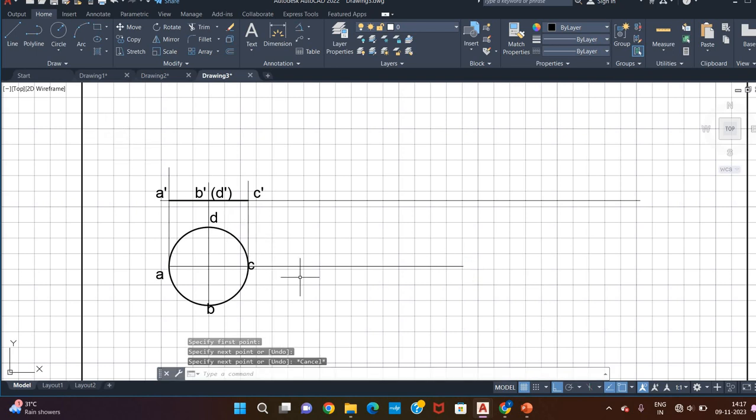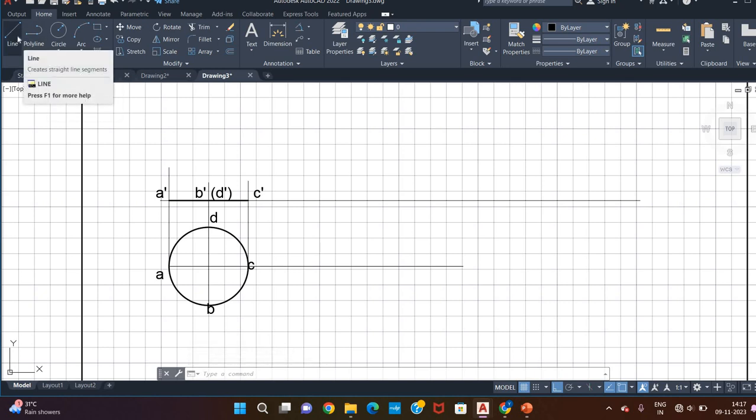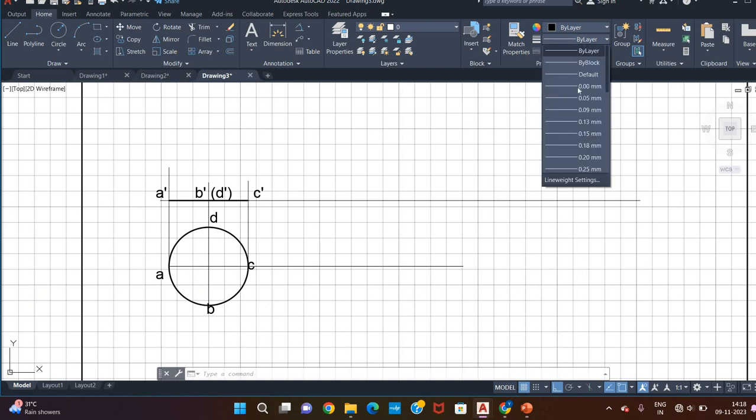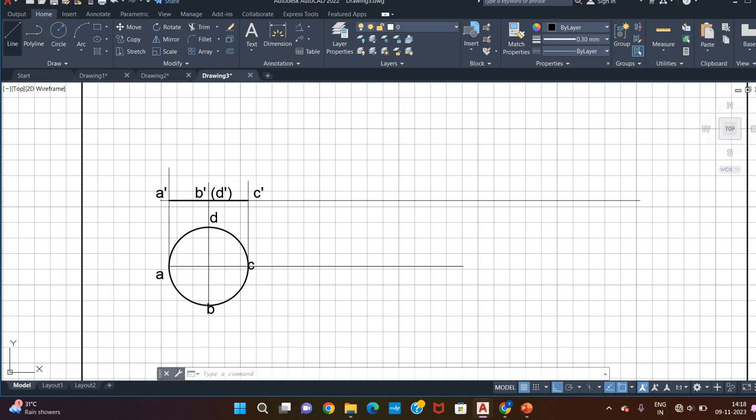Okay. Then in this line, we need to take that 30 mm. That minor axis will come here, and for this, it will become the major axis. This line will not shrink, but the AC line will shrink when the inclination goes. When we keep inclination, only the AC line will shrink. So take a line, draw the line for 30 mm.